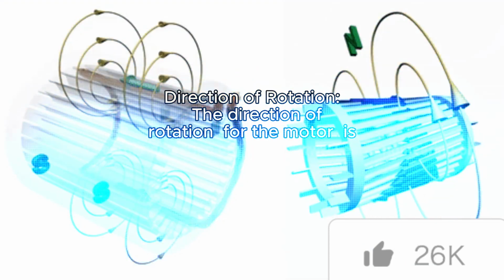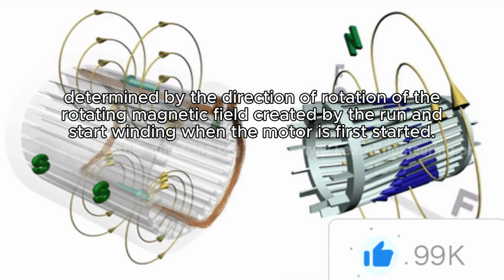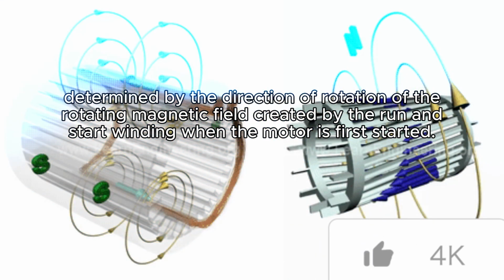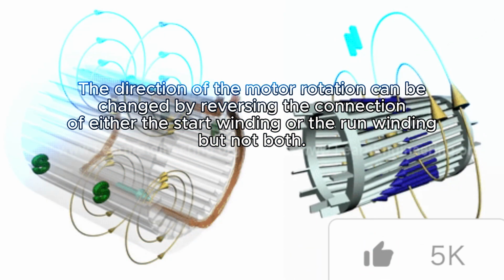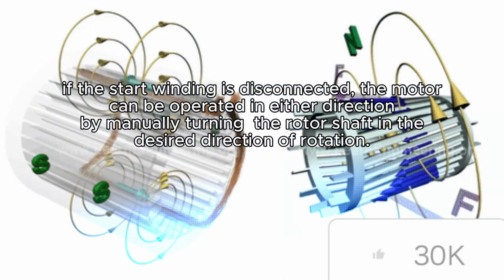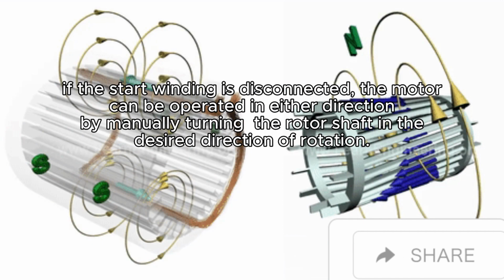Direction of rotation. The direction of rotation for the motor is determined by the direction of rotation of the rotating magnetic field created by the run and start windings when the motor is first started. The direction of motor rotation can be changed by reversing the connection of either the start winding or the run winding, but not both. If the start winding is disconnected, the motor can be operated in either direction by manually turning the rotor shaft in the desired direction of rotation.